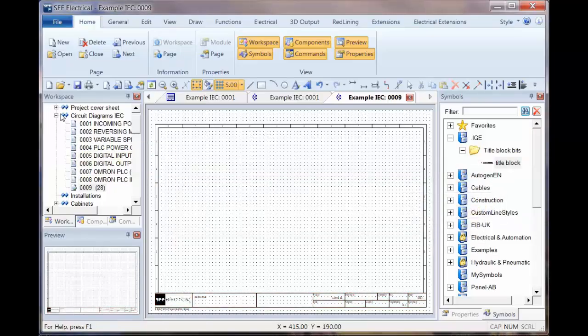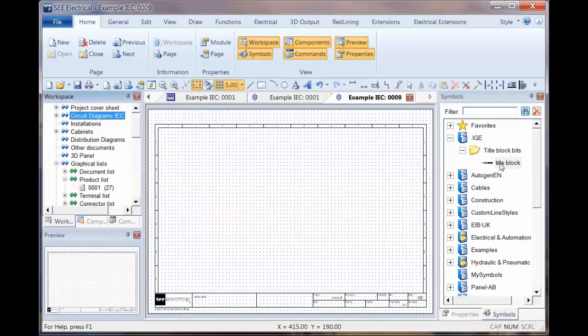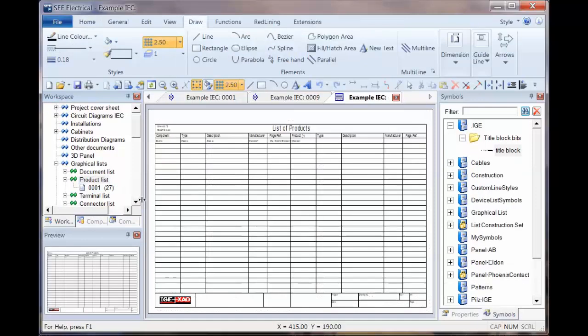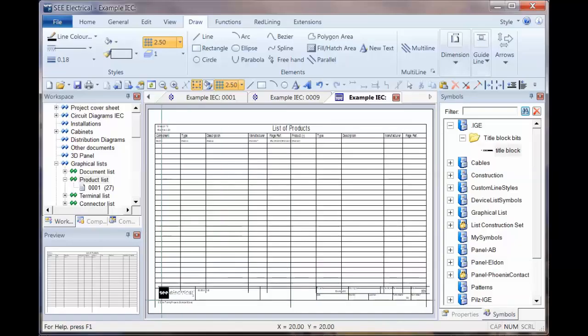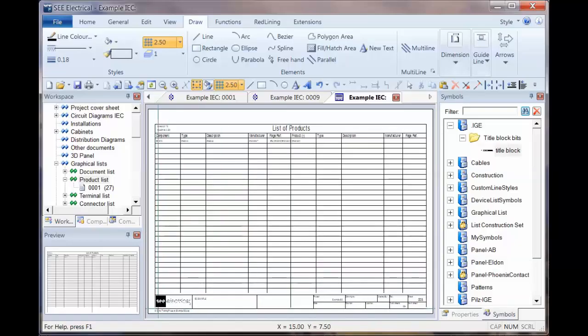Now if I go back to one of my reports, I've now got that in my catalog. I can use that for a standard report, and there are several. We can actually go to load page template. We can see the information there. We can then Control A, right click and explode, and already the title block at the bottom is separate. We can select it, we could delete it, and then we could just drop in the correct title block in its place.